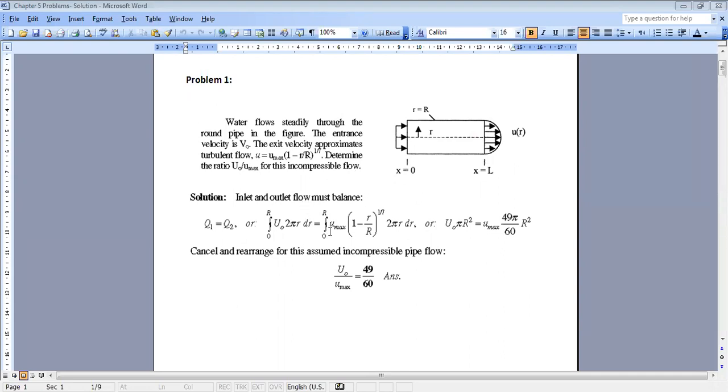Yes. Is the velocity profile at the end the same for all the pipe, or just for that little part? Once it is fully developed, it will be the same everywhere. But you have a certain region where it is changing. We say that the profile is developing.